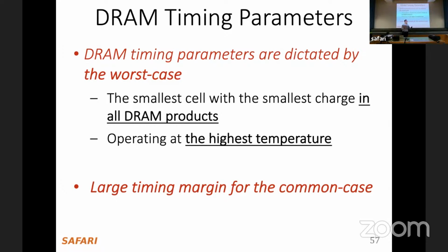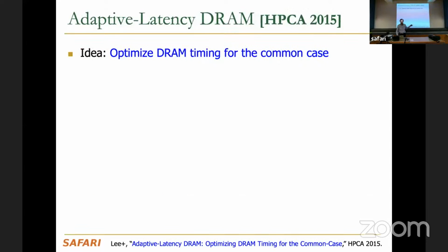So those processors are binned to be operating at higher frequencies. Some other processors where they have slow transistors by luck, let's say, in general, they're binned to be operating at lower frequencies. So in the processor industry, this binning is already done. In DRAM, some of that binning is already done in terms of frequency, bus frequency, but not in terms of latency. So the latency binning is not done in DRAM that much because it increases the testing cost, as we will see. So there's a downside to it, but the benefits, I believe, are relatively large, as this paper shows.